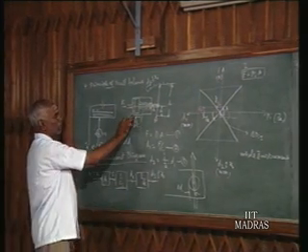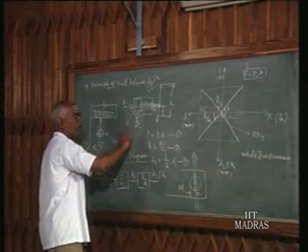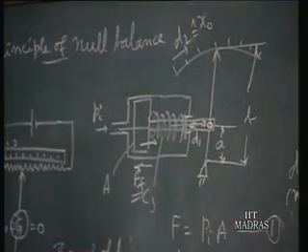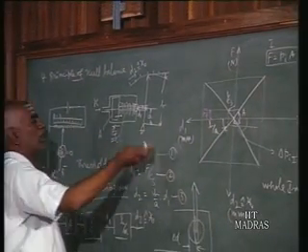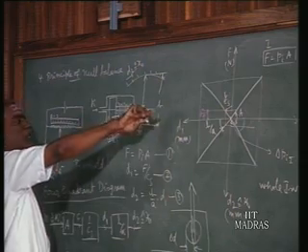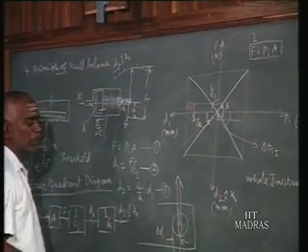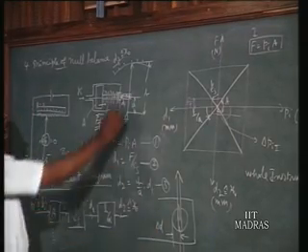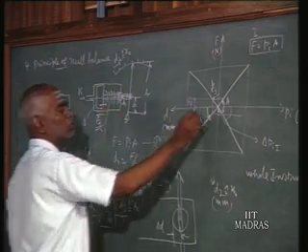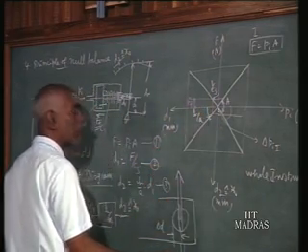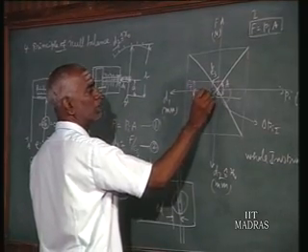Now suppose we have overcome the friction force, then the piston starts moving. Still the pointer will not move, because you have to have the motion of delta D before the pointer moves. After overcoming the friction, we have to move the piston again until this play is overcome. So it is in series. Delta D is a displacement that has to take place in the piston rod, and D1 is the piston rod motion. So after this point, you have to put delta D.